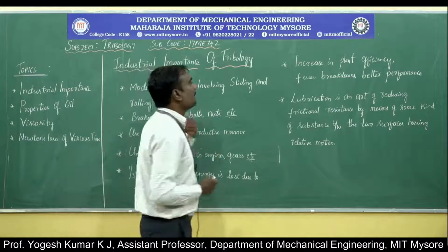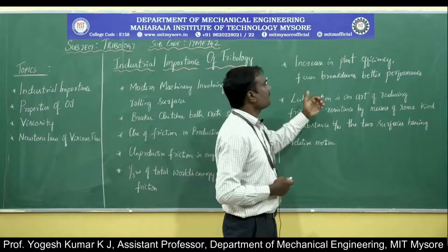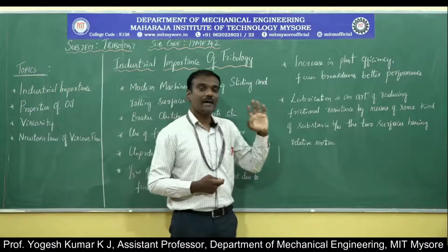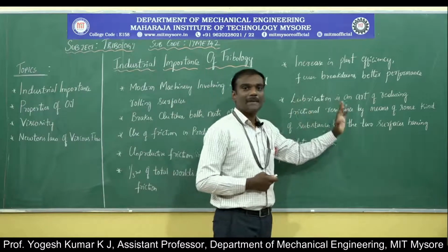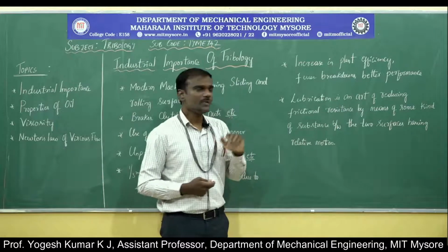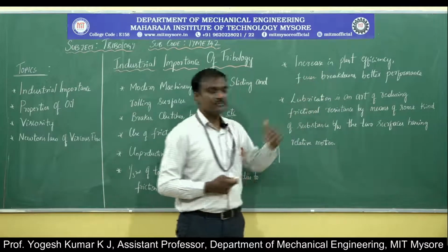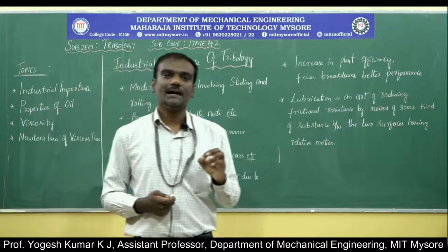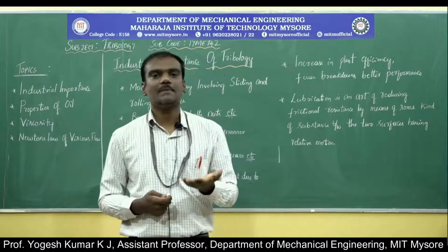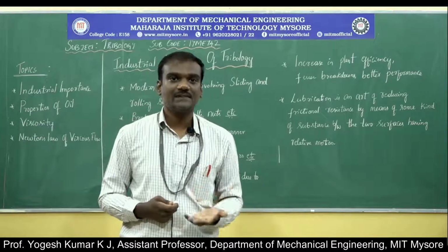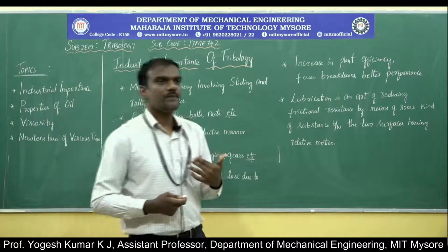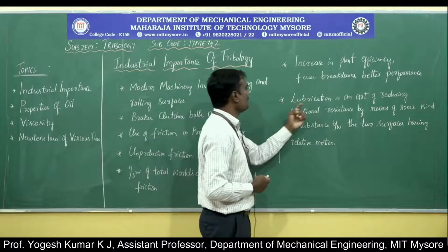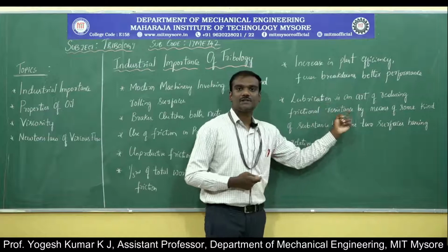So thereby the performance of an industry, as well as the efficiency of the industry or machinery, is going to be enhanced with the research that is happening in the field of tribology. Then how are we going to minimize wear? We are going to minimize this by taking certain precautions. We will select a material which has wear resistance, and if those materials are not selected in a proper way, then we have one more option: lubrication comes into the picture.